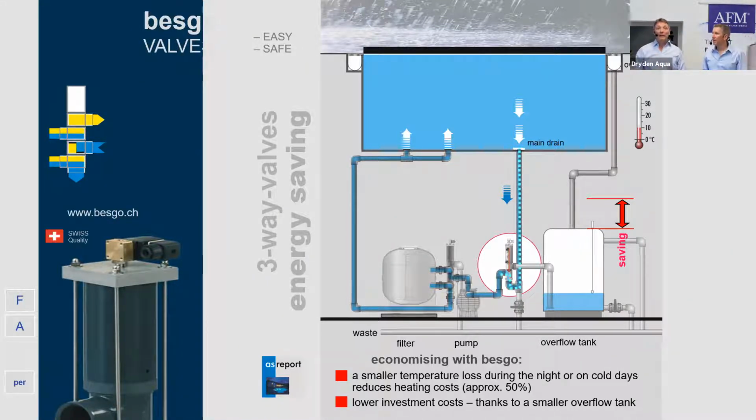And thirdly, and that might be the most important one for you, you can reduce the size of your balance tank, because you're not pulling the water from here, you're using it from here. That's big, especially if the filters are bigger. These are significant savings in dollars and in room. And again, don't take these dollars and give them to the customer. Take these dollars and invest them in better filtration, variable speed pumps, flowies, and of course AFM.